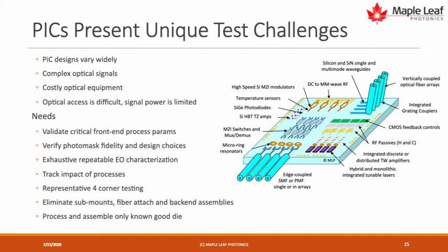you want to be able to also track how the process of fab changes the behavior of the chip. So you may have strain. If you have a silicon nitride layer, strain management is a good example, a big challenge. You'd like to see where the strain is being introduced and whether it can be relieved.